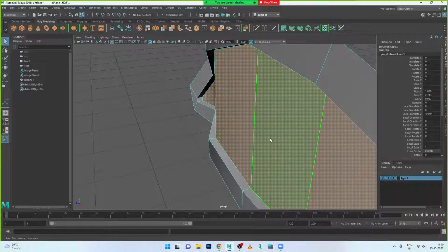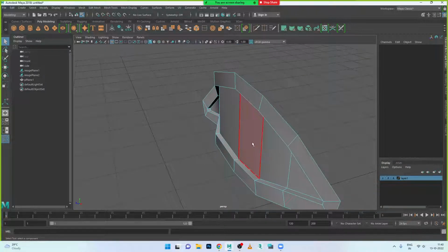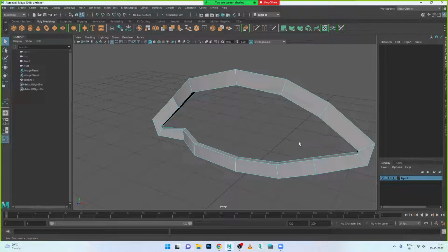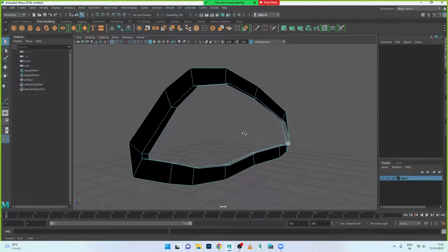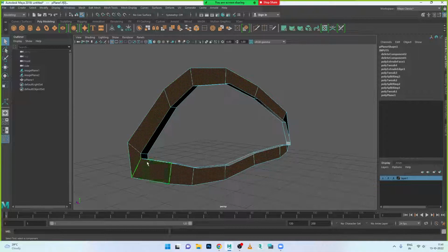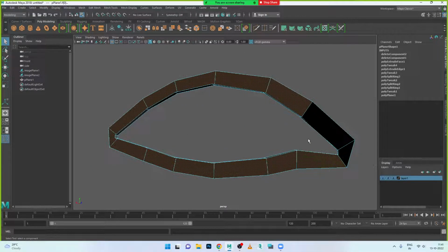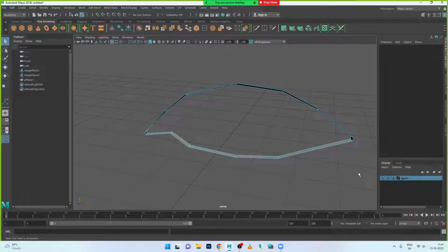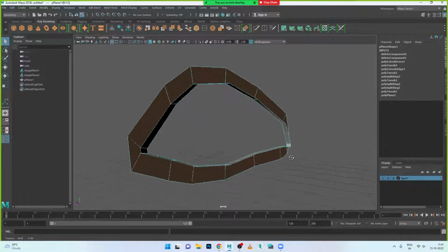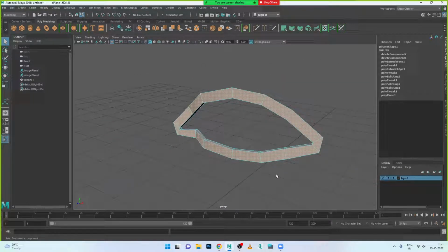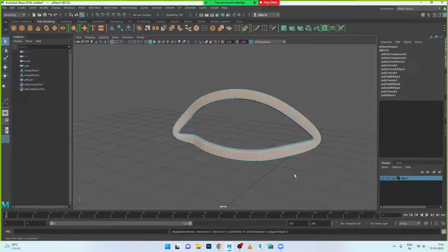Right click again, faces, and delete all these faces. There are no faces over here right now. Maybe we got some double faces. I am deleting these double faces if I have anything. It is proper only, right? Delete the double faces. Right now we have done, so this is okay. Now let's apply the smooth and see.